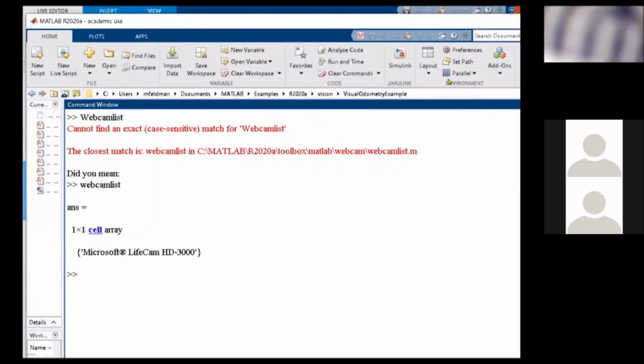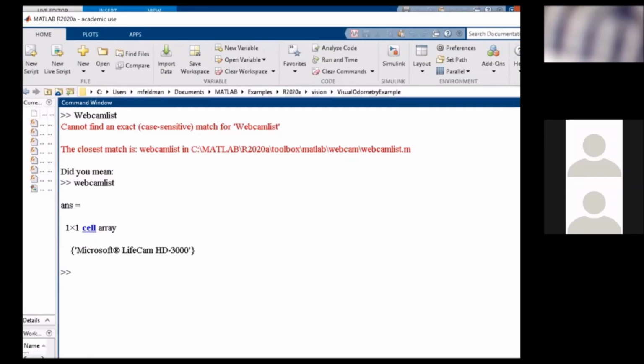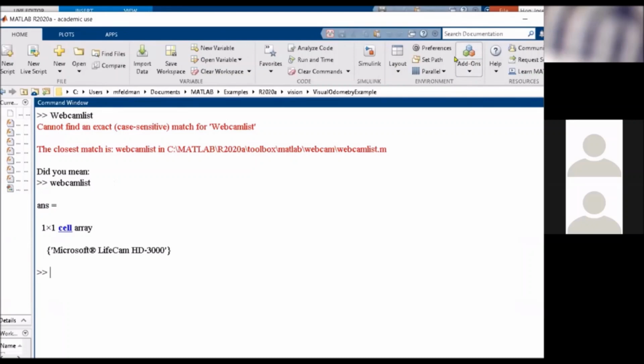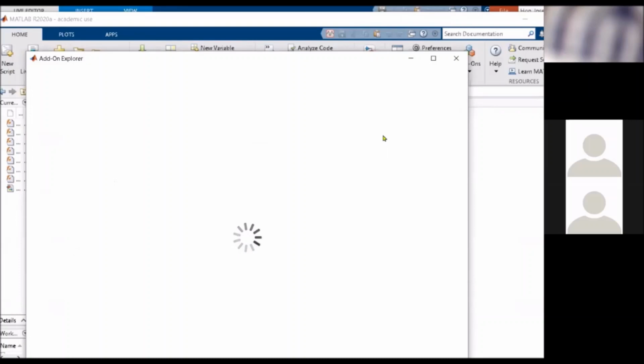You have no code, Simulink, environment here? Maybe just enlarge your window. Maybe this way you can see add-ons. Just enlarge it in the horizontal way. Maybe this way. Can you see these add-ons? Yes. Now press this small triangle button and go to Get Hardware Support. Can you see it? Yes. And in this Get Hardware Support, just choose USB. Thank you. You're welcome.